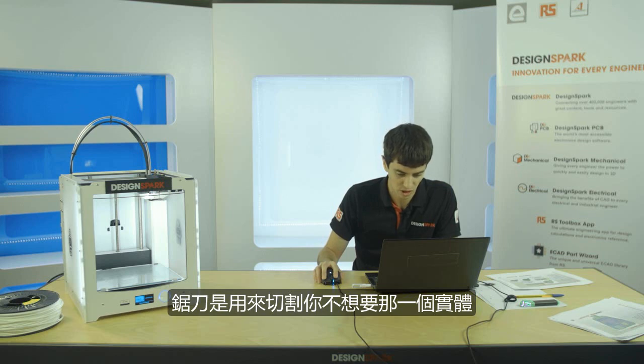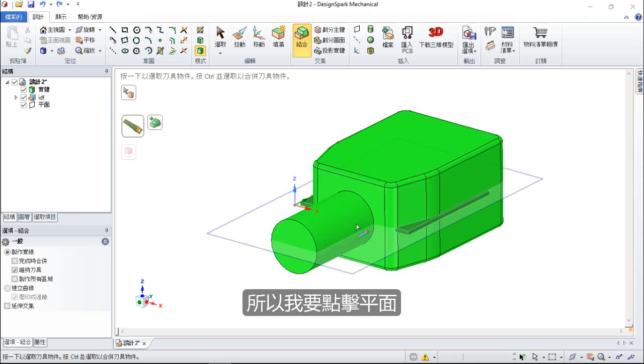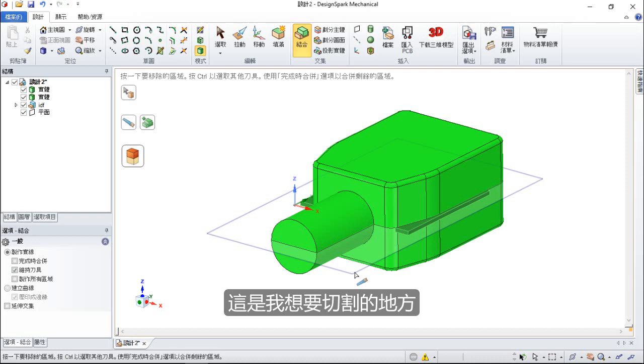So the saw means what item would you like to cut along? So obviously we would like to cut along the plane. So I'm going to take my saw cursor and click the plane. So this is where I'd like to cut along.